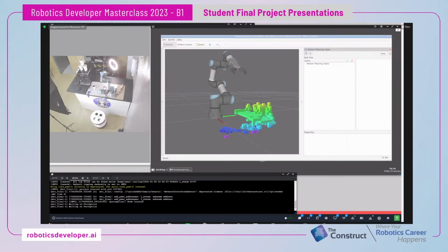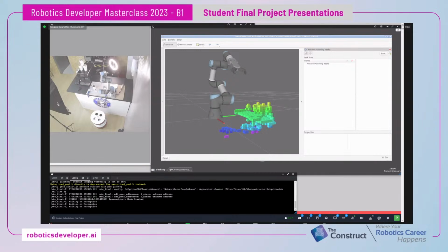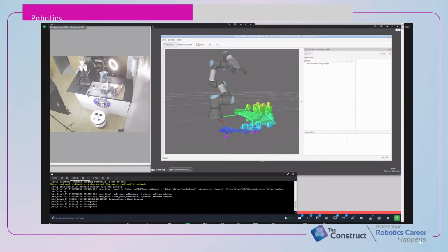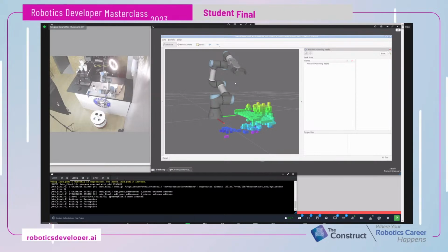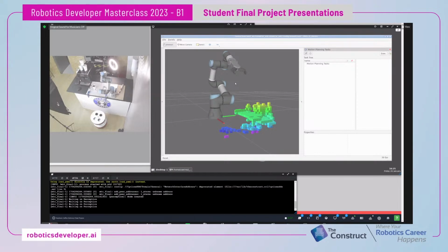And then added joint limits to the arm's joints. By default, they're allowed to operate in effectively a continuous rotation mode, and that was limited to a single rotation of minus pi to pi, and this incidentally improves all of the plans, constraint or not.